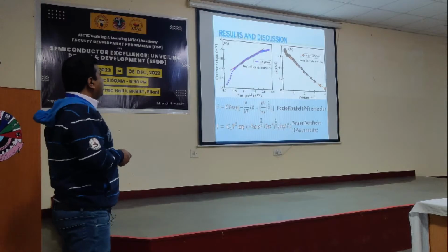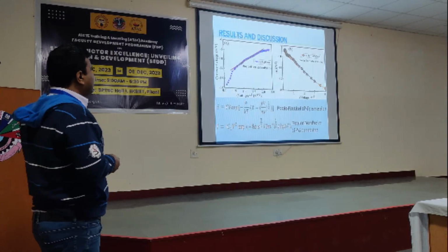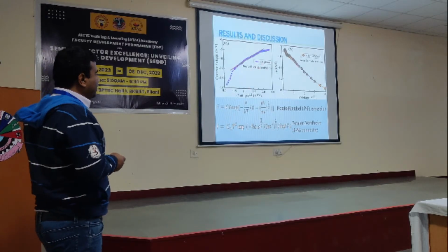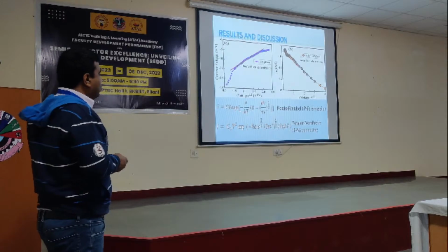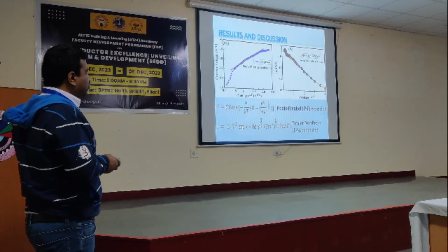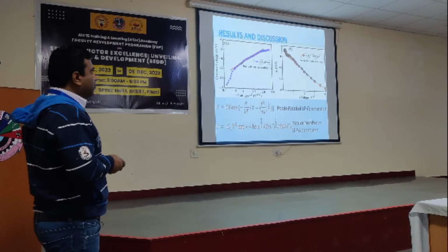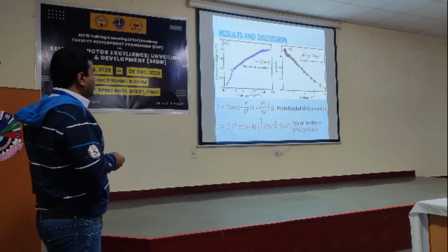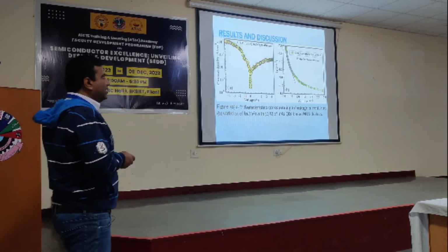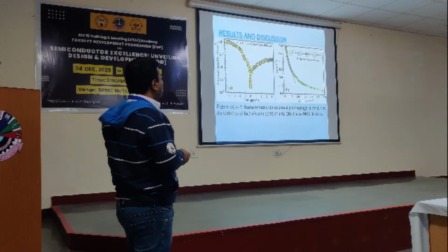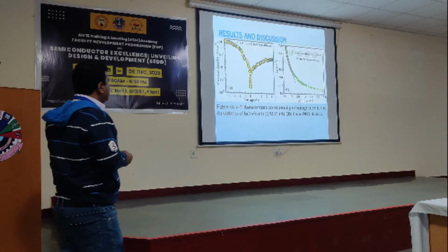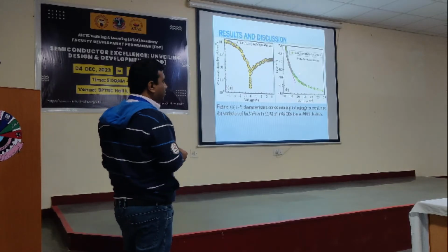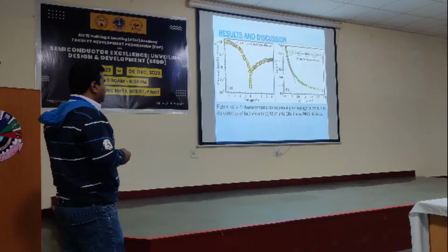Now these are the I-V characteristics of the three kinds of devices. You see, for the first device where only ZrO2 is there, the current follows Poole-Frenkel emission. You just plot this in Poole-Frenkel emission. This is the corresponding formula, and the passivated surface also follows Poole-Frenkel emission. And this is your final device, the quantum dot enabled device. In the quantum dot enabled device, the leakage current density is 10 to the power minus 6, and in that case the current follows the Fowler-Nordheim tunneling mechanism.